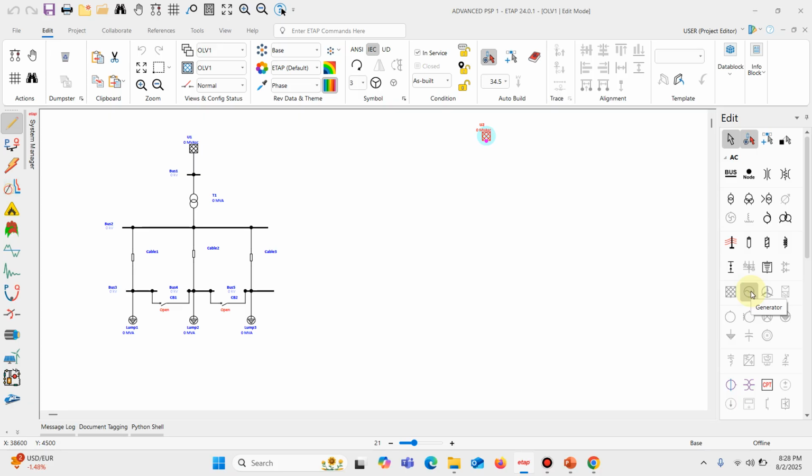There must be something, preferably a bus bar in between. But we can connect a bus. So this is one of the benefits of the auto build. It shows you equipment that are compatible and equipment that are not compatible. So let's say we want to connect a bus. Now the traditional approach which we used previously was to click, come over here and drop, then connect. But this time around, using this auto build, we just click on the bus and it is automatically connected.